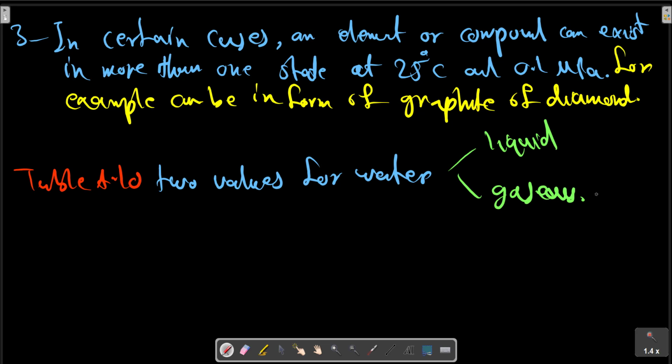This is analogous to the situation we would have in the steam tables if we let the enthalpy of saturated vapor be 0 at 1/10 megapascal pressure. In this case, the enthalpy of liquid would be negative, and we would simply use the negative value for the enthalpy of the liquid when solving problems.